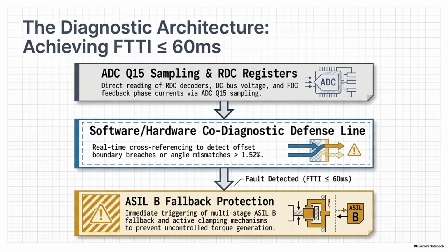ROL is the crucial boot sequence. It happens every single time the motor is powered up, but is still completely stationary. The power control system, the PCS, performs this sort of covert diagnostic handshake. It injects a very specific high-frequency voltage signal into the stator windings. Wait, if the motor is completely stopped, why are we injecting voltage? Doesn't that make it try to spin?